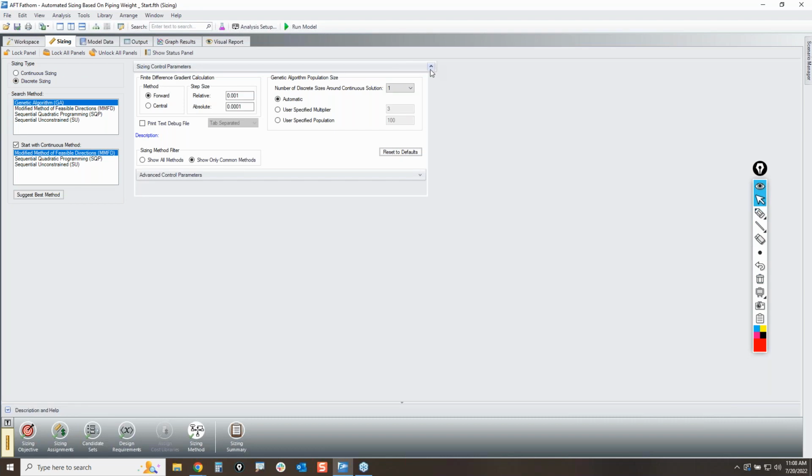Also, stick with the default parameters here. That way it works as intended. You can go in and manipulate this all you want, but I would highly recommend that you really fully understand all of these methods and really read the help files to know what you're doing. Because if you change the values, you can very well not have good convergence or correct results.